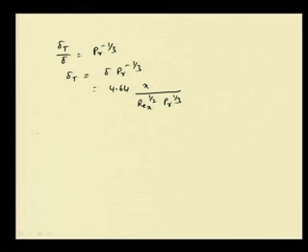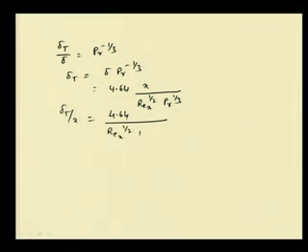Now, for delta t, the thermal boundary layer thickness, we can write delta t by x as we have written in the case of the hydrodynamic boundary layer. So, it is 4.64 divided by Re x to the power half Prandtl to the power 1/3. So, the difference between the hydrodynamic boundary layer and thermal boundary layer thickness is a factor of Prandtl number to the power 1/3.